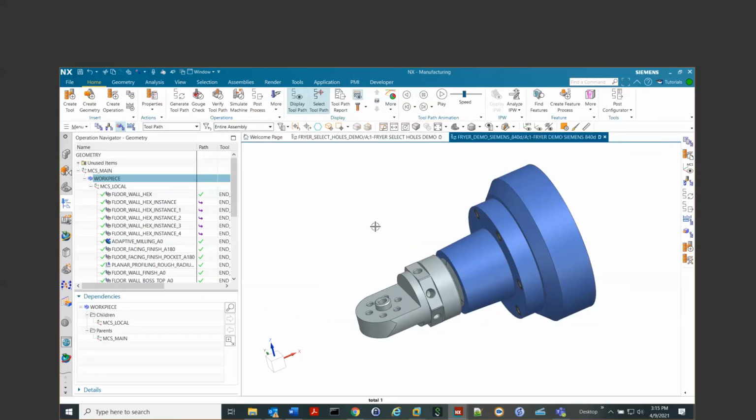If it happened on a line that is coming up that I haven't grabbed yet, then it would grab that data for sure. And if I'm within that 500 block buffer, again, that has already been transferred to the high-speed memory of the system, right? So at that point, I wouldn't know it if you were changing something within that line segment, because from our perspective, even if we're cutting it right now, it's already passed. But Mike, can you speak to maybe any protection that the Team Center side of the world might put on that? Because we haven't tried it, so I don't know what would happen.